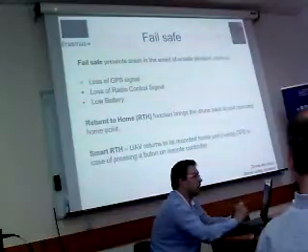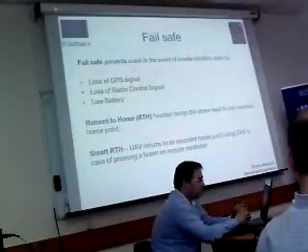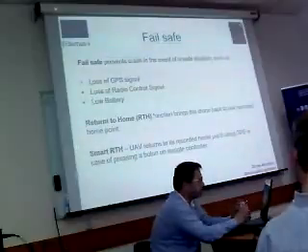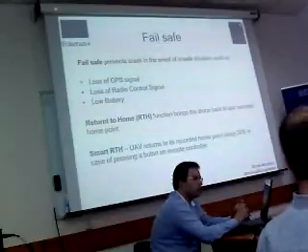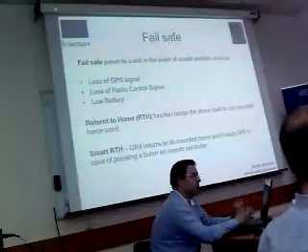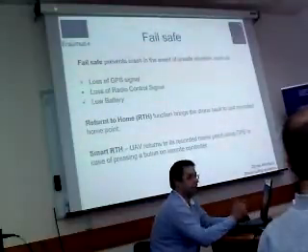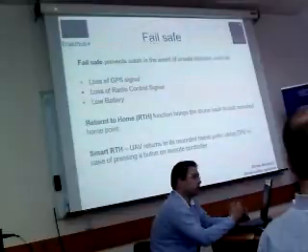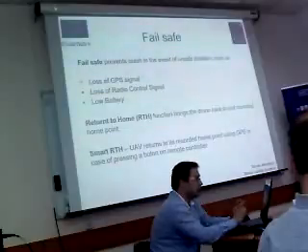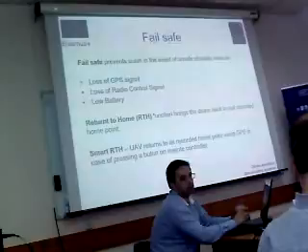Another case is loss of the ground control signal. The failsafe activates when the remote signal is lost for more than 5 seconds. It depends on the kind of UAV, but the default setting is to ascend to a preset altitude and return to the home point. Another option is to have the drone go into hover mode until it either reacquires the signal or runs out of battery and lands automatically. The third option is to set it to land wherever it is as soon as it loses signal.